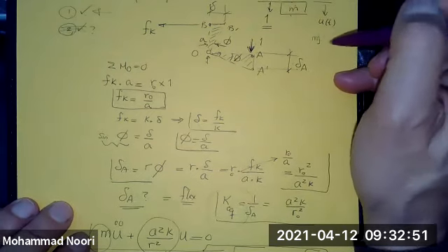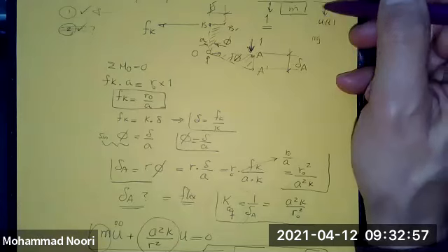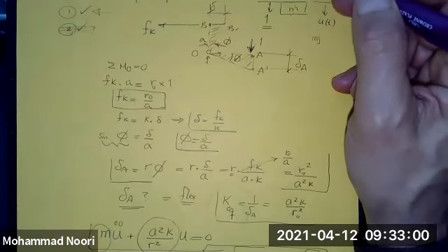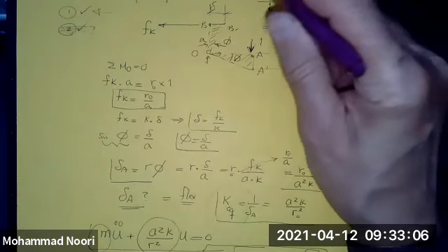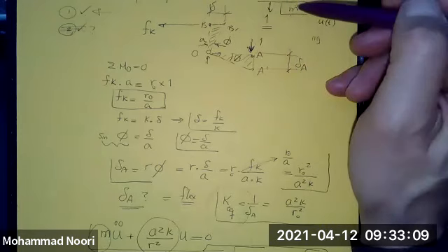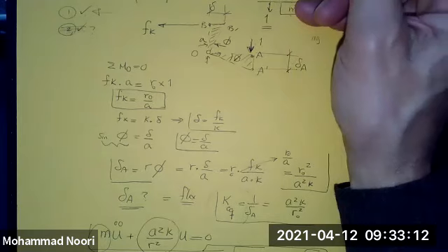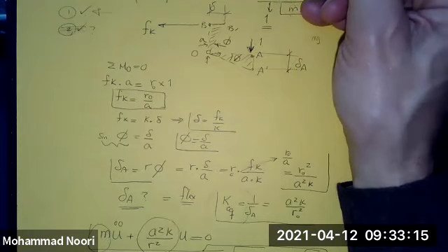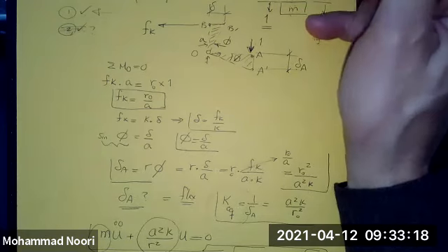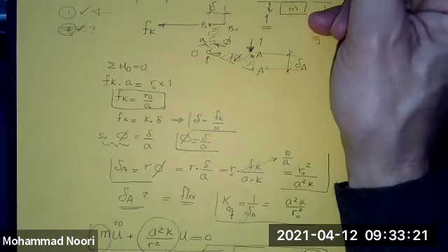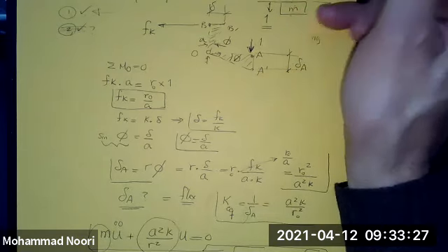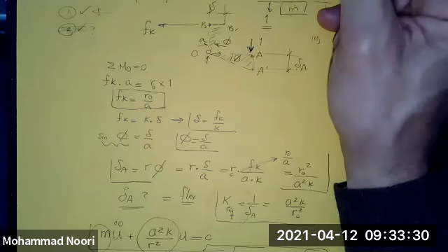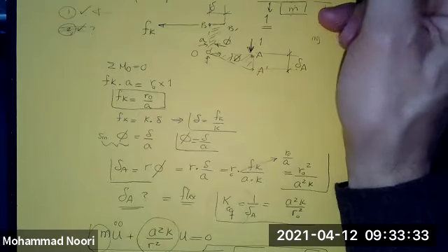Assuming the displacement is very small and you're starting the motion from equilibrium, the spring has already been stretched through its static displacement due to the application of M. So the configuration I'm showing you is from the point after it has already gone through the static displacement.